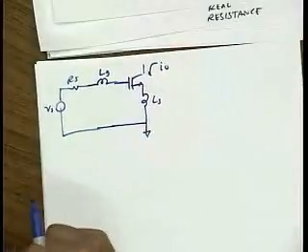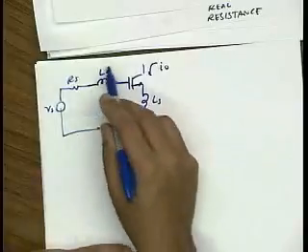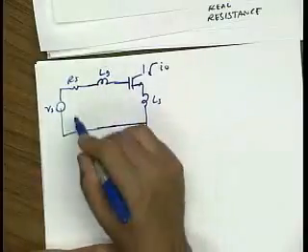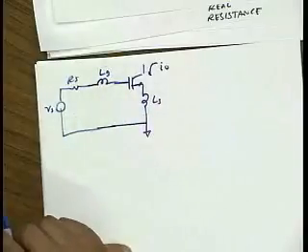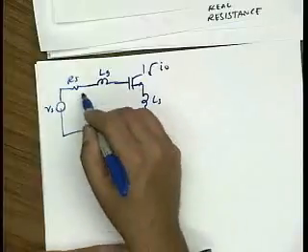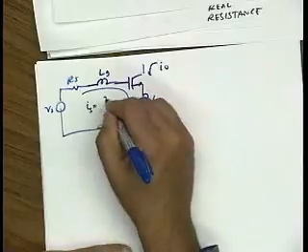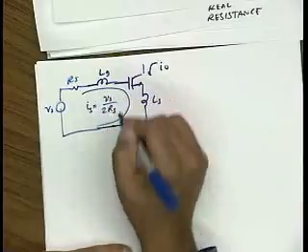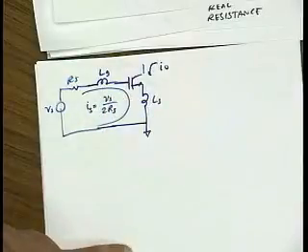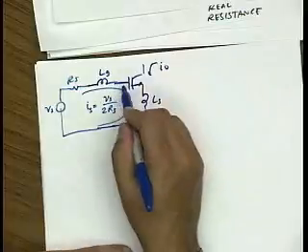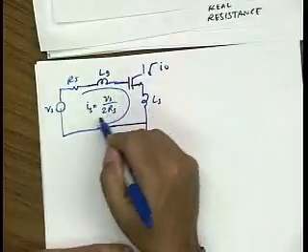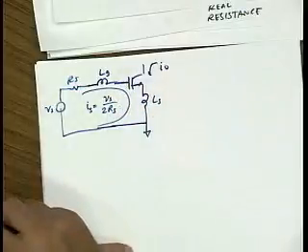Okay, so notice that by placing LG here, I've actually put my circuit in resonance, right? So the input current, IS, is simply VS over 2 times RS. Now that's approximate because there's also RG, but I'm assuming that RS is larger than RG.